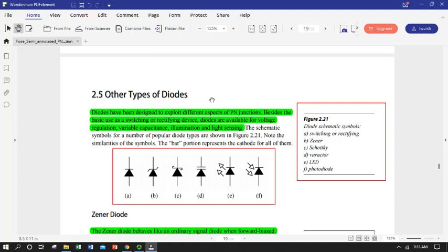It isn't just a principle, it's an action plan. So please excuse my use of Kirchhoff's voltage law as a verb, and you can KVL your circuit, but maybe don't use that terminology as such in the workplace, unless your boss does the same thing. So, but you've now seen the power of Kirchhoff's voltage law using a diode model as just an opposite oriented voltage source primarily. You will use that again and again in very complicated circuits that become simple, because you can do that.